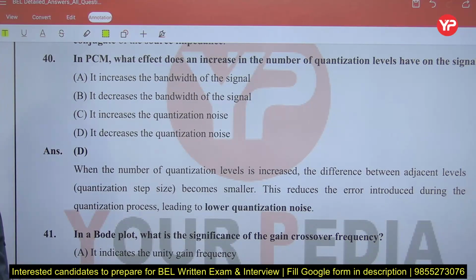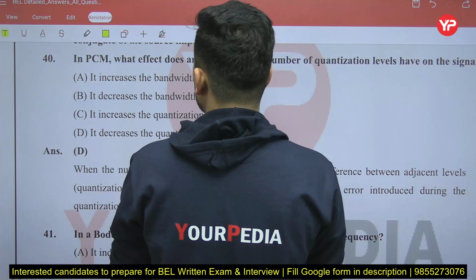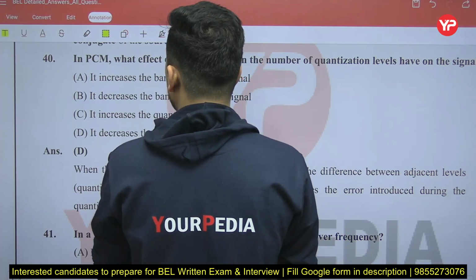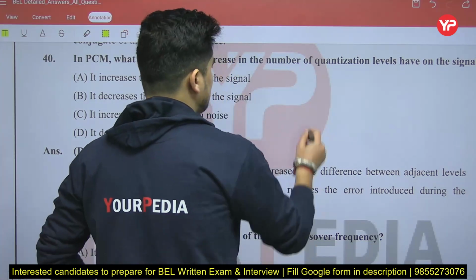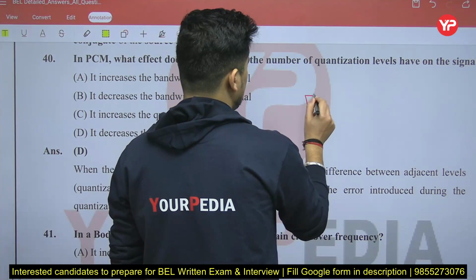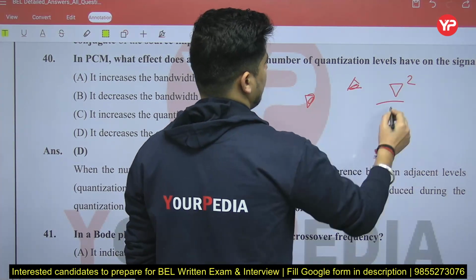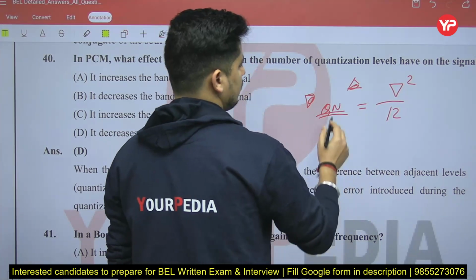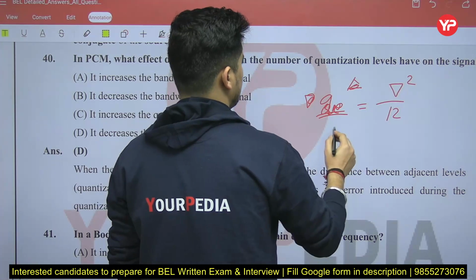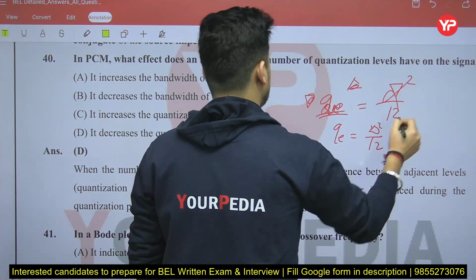Next one is, in PCM, what effect does an increase in the number of quantization levels have? Increase the bandwidth, decrease the bandwidth of the signal, increase the quantization noise, decrease the quantization noise. See, basically the quantization noise, you can write quantization error or quantization noise, is delta square by 12.